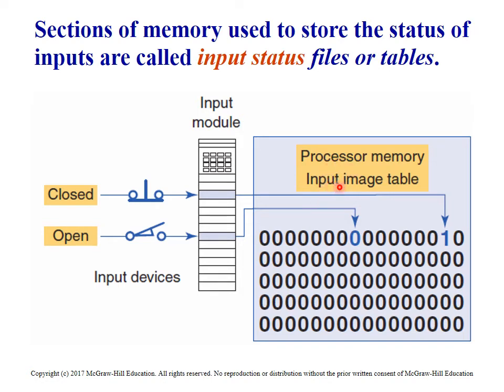The processor memory input image table. I mentioned a little bit of that before, where I'm talking about data tables. The processor, the CPU, the whole PLC process does nothing more than manipulate data tables. That's all it does. So when you think PLCs, I want you to think data tables.